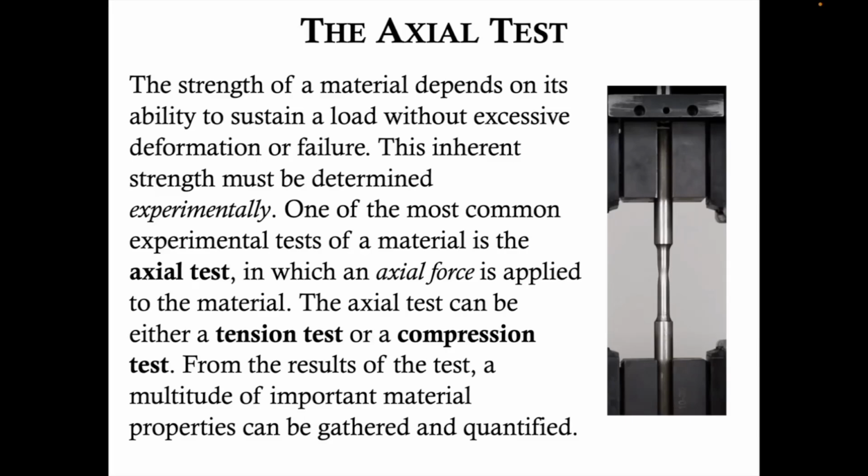Let's discuss the axial test. The strength of a material depends on its ability to sustain a load without excessive deformation or failure. This inherent strength must be determined experimentally. One of the most common experimental tests of a material is the axial test, in which an axial force, also known as a normal force, is applied to the material.